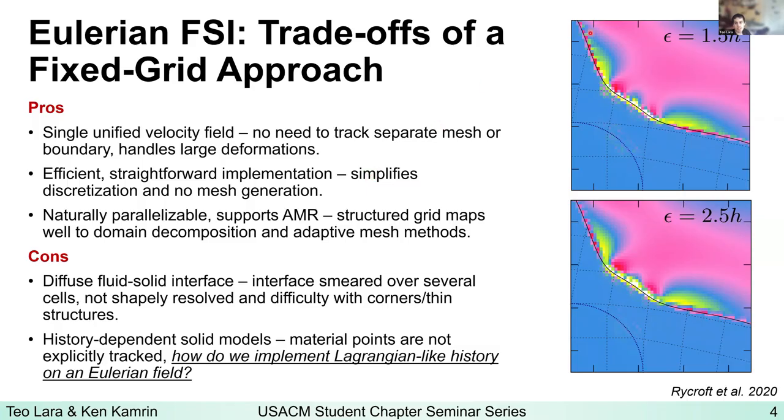Meaning that the interface size can actually impact the physics here. If we look here on the two images to the right, the top one has a slightly smaller interface than the bottom one. You can see that the results are the same, but there are sort of non-negligible changes due to this change in the interface size. You have to be careful about how you treat the actual fluid-solid interface in these simulations.